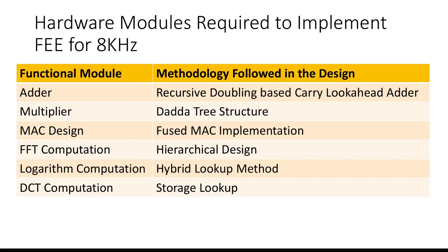Methodology followed in the design for the functional modules. Adder: recursive doubling based carry look-ahead adder. Multiplier: data tree structure. MAC design: fused MAC implementation. FFT computation: hierarchical design. Logarithm computation: hybrid lookup method. DCT computation: storage lookup.